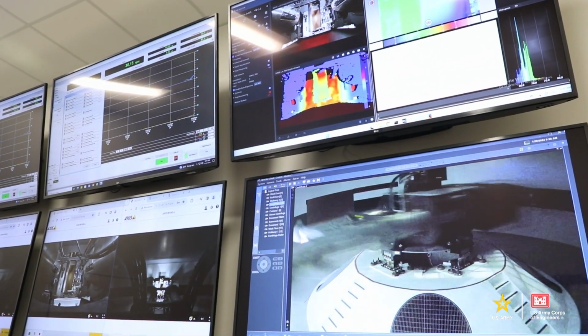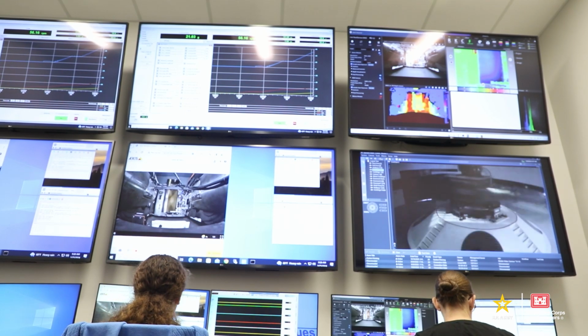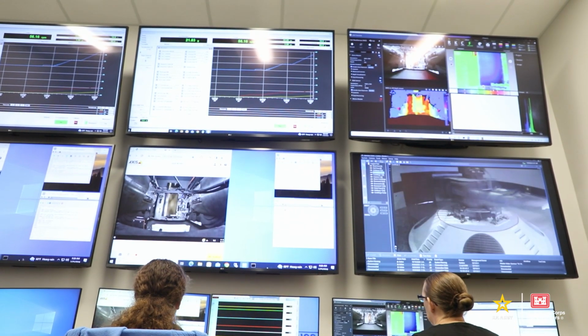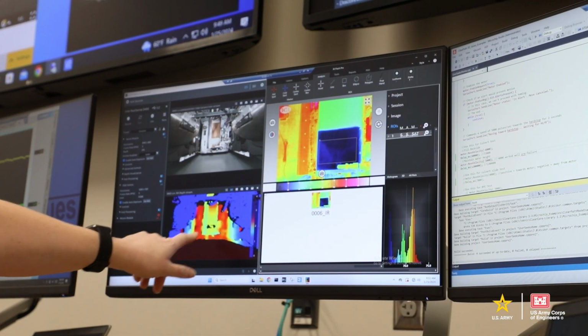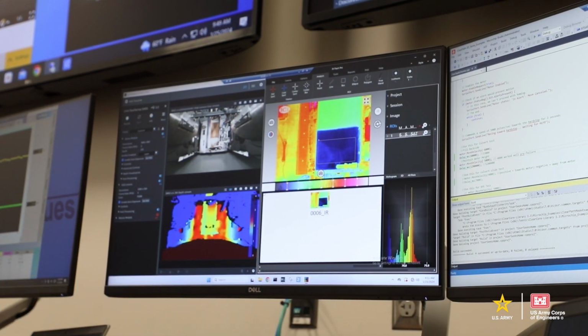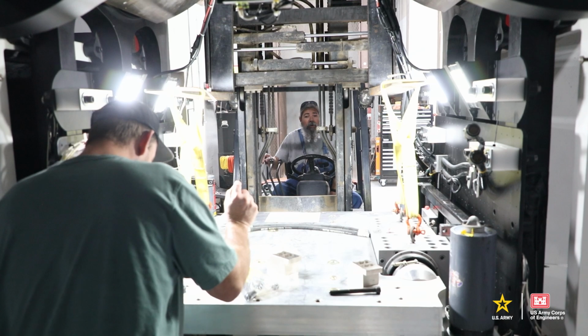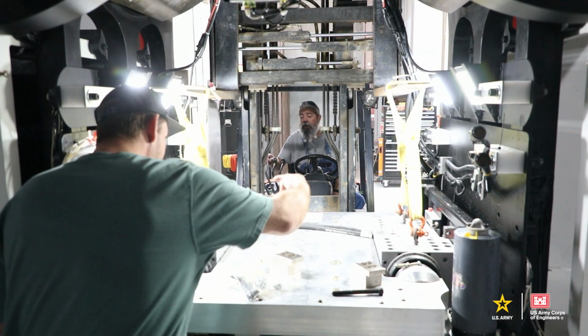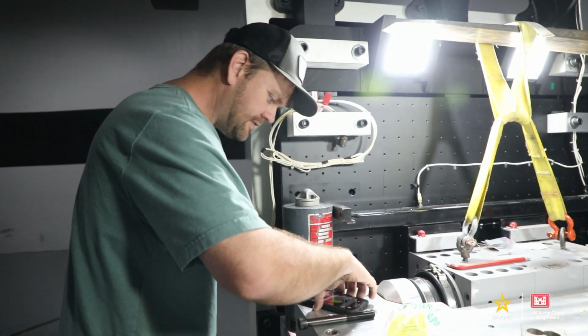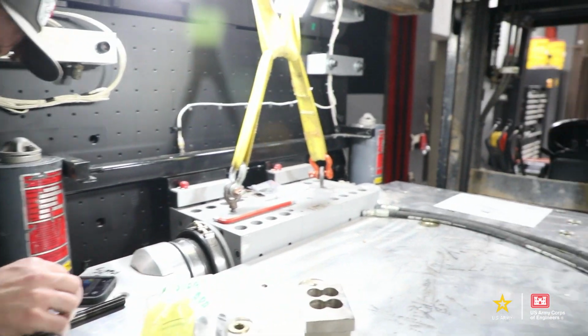And two, we wanted to see, can instruments or monitoring help us identify odd changes or things that we wouldn't expect. We had to make a false bottom for it to build the levee on top of so the water could come off the other end. We had to make a soil catch and a V-weir to measure outflow. We had inflow and outflow readings on it.